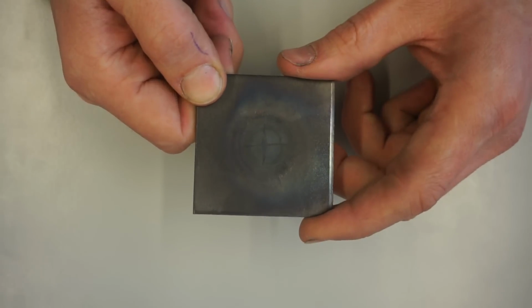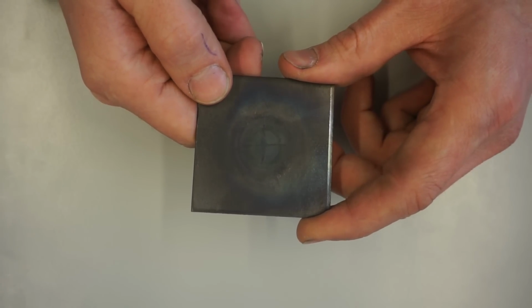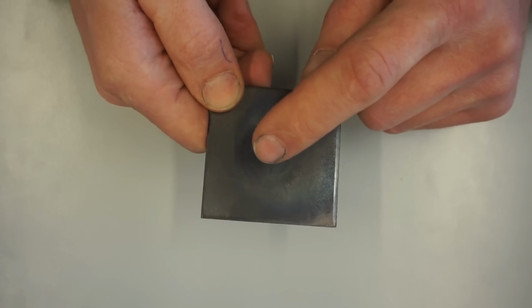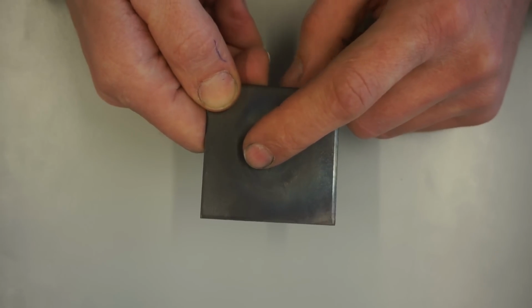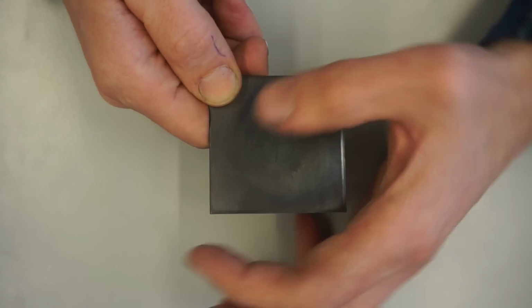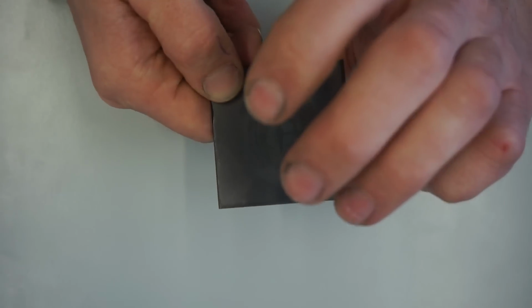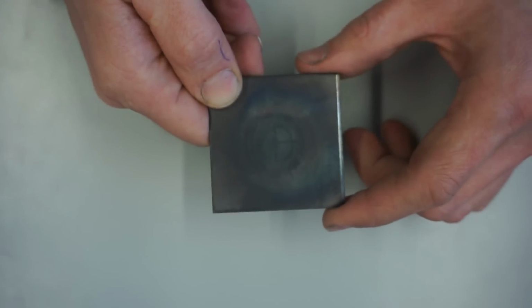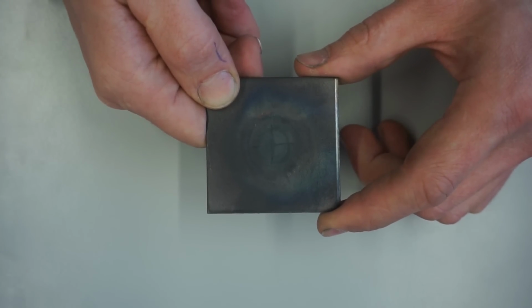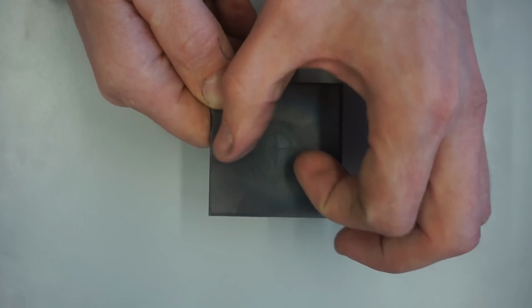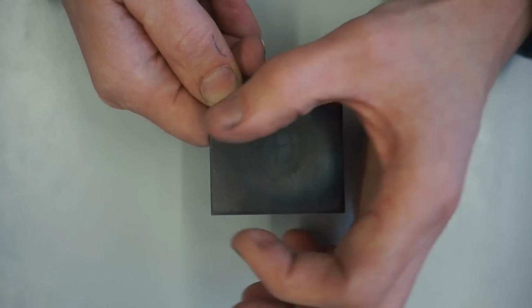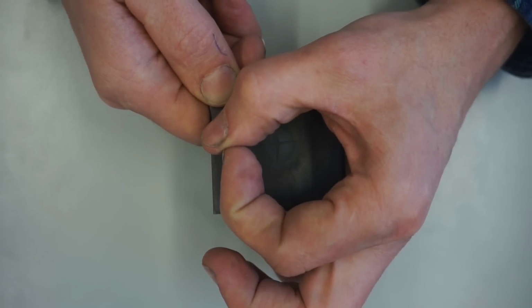But why does this area thicken anyway? Well, as we heat the spot with the torch, it wants to expand equally in all directions. It can expand quite freely in thickness direction because nothing much constrains it there. But the expansion in the sheet's plane is very much hindered by the cold surrounding rest of the sheet.